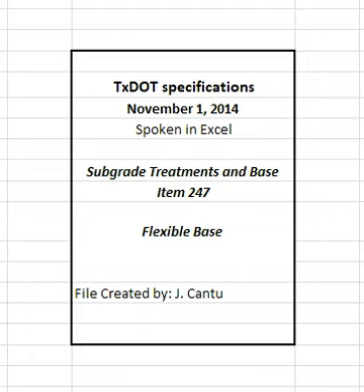4.6 Ride quality. This section applies to the final travel lanes that receive a 1 or 2 course surface treatment for the final surface, unless otherwise shown on the plans. Measure ride quality of the base course after placement of the prime coat and before placement of the surface treatment, unless otherwise approved. Use a certified profiler operator from the department's MPL.